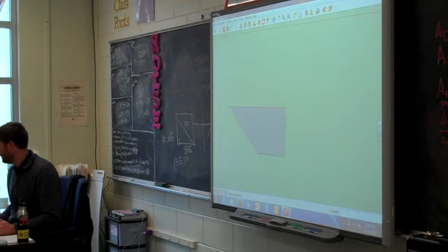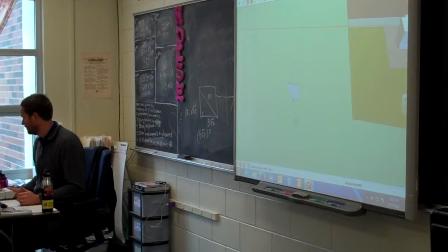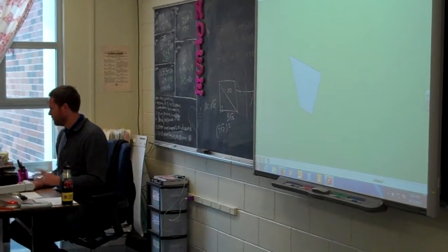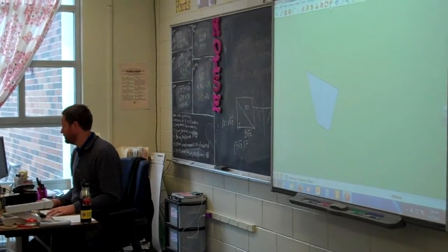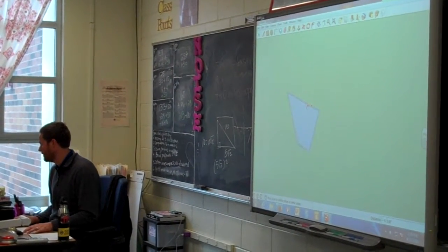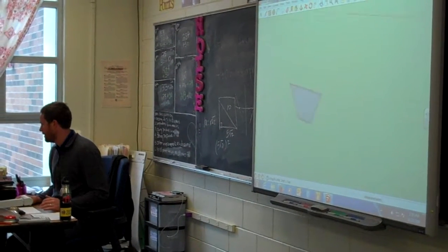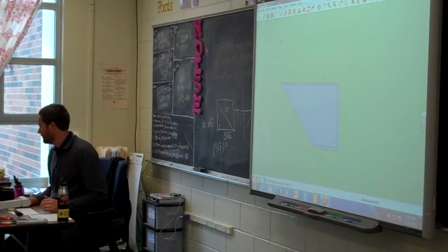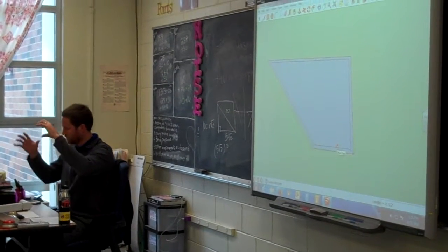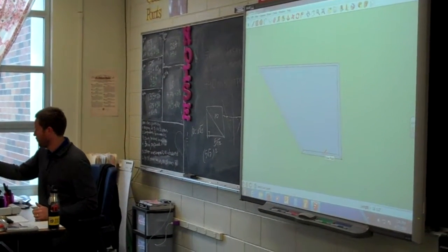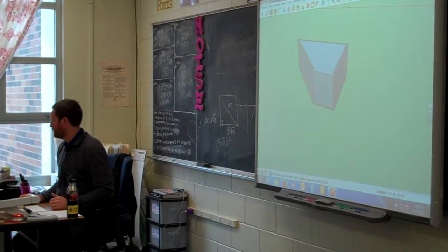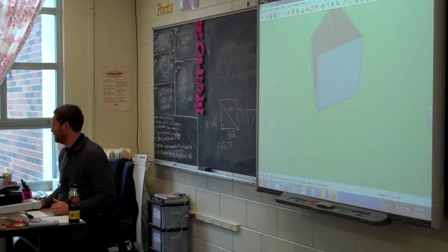By navigating, you can go under, below, or above, and I want to make walls. This is a new tool we haven't used yet. It's called the offset tool, and it will create a mirror image of the outside shape. Let's say the entrance is right here. I plug up this entrance by drawing a line there to finalize that shape, and then with push-pull I can pull up a three-dimensional wall, so we can enter in.